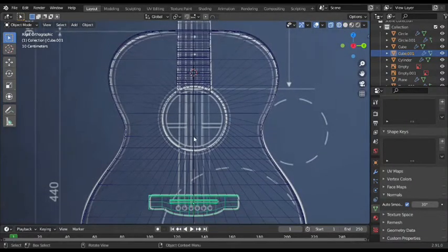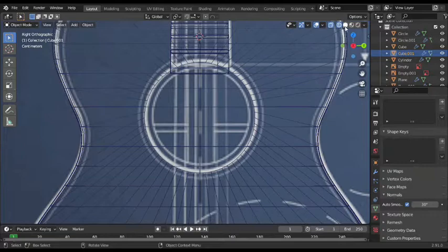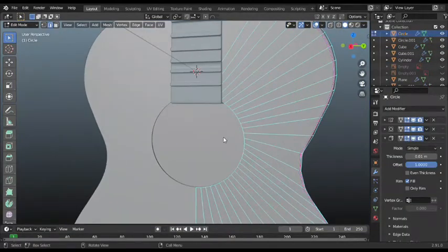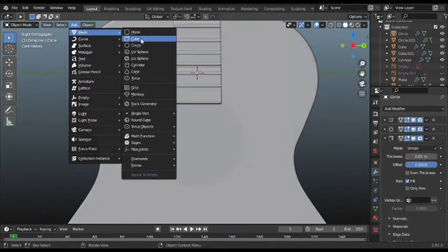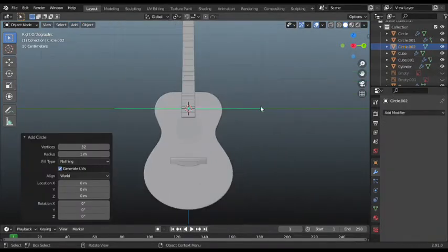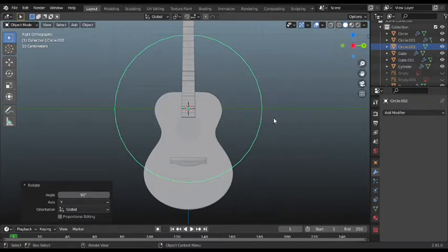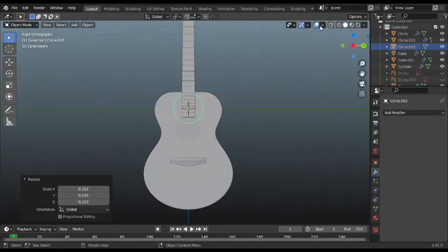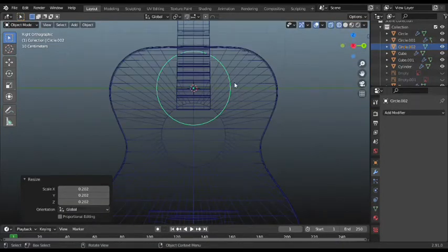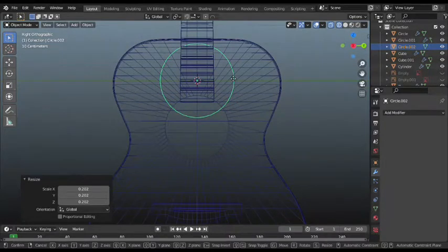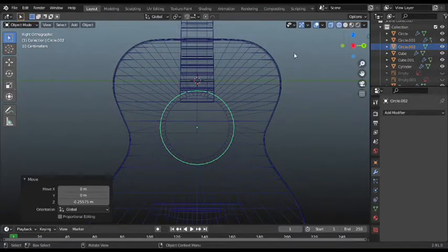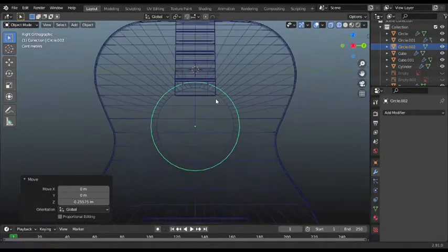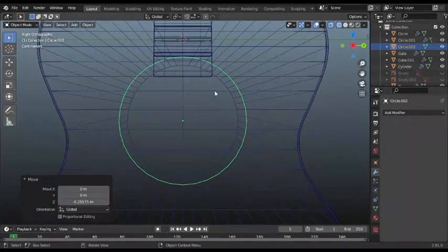Now I guess I have to decorate this part. It's looking very empty, so for that I'm gonna add in a different object. Add circle, rotate Y 90, scale it down, enable the extreme mode so that it's better visible for me. G Z, not extreme mode actually, I confuse between X-ray and wireframe. Actually this is the X-ray mode and this is the wireframe mode. This will help you see through the object, basically the vertex and the edges.